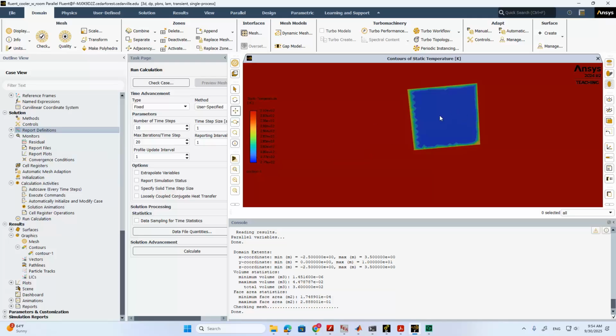You should be able to get, for example, the temperature at the very center of the water region. It will be able to monitor how its temperature varies with time. It also can monitor multiple spots, for example another point in the air region in the cooler, in the aluminum container, in the foam, and in the room air. You can set up a bunch of different monitoring locations, and monitor how the temperature varies with time. This is the end of the tutorial.